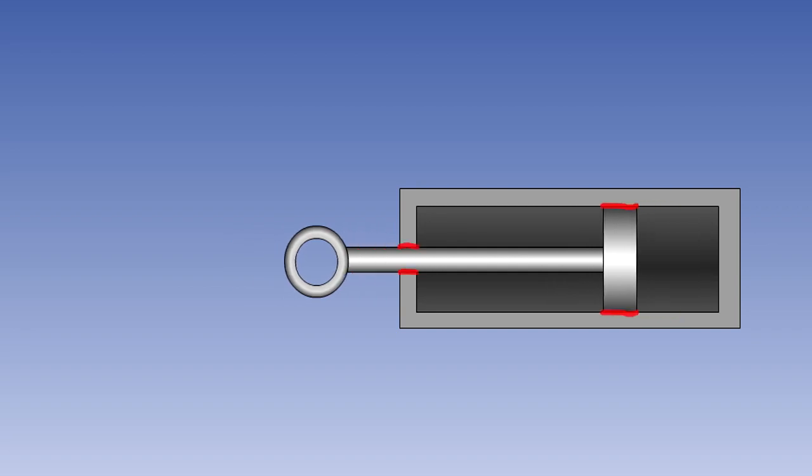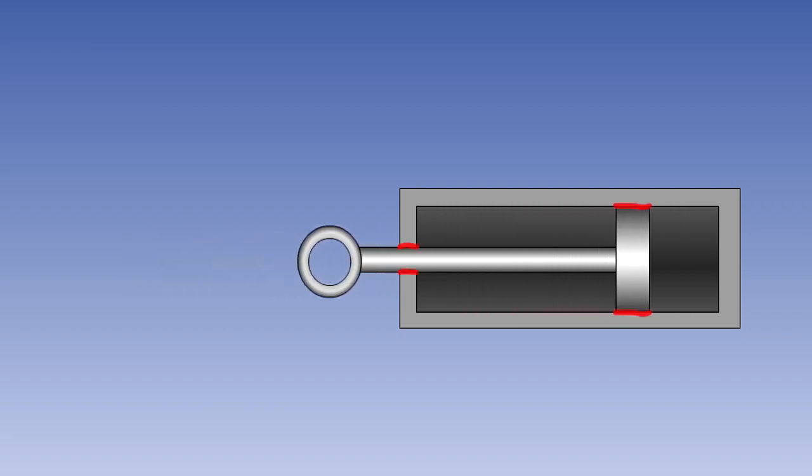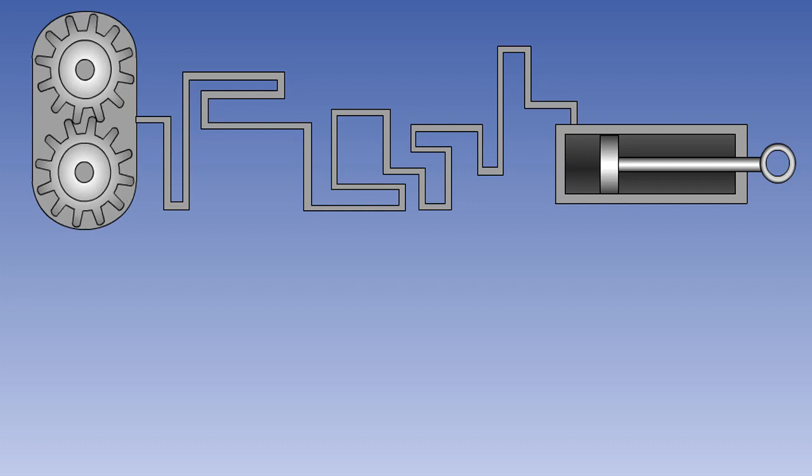Large bore pipes and frictionless pistons would allow nearly 100% of the force to be utilised, but would incur large weight and cost penalties. Friction between pistons and cylinders, and piston rods and bearings, cannot be completely eliminated. It can only be lessened by good design and workmanship.